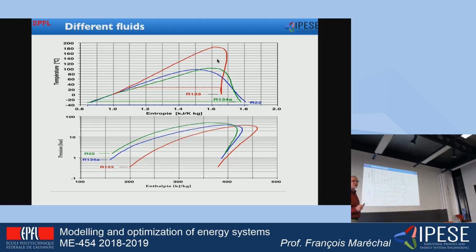Right, so I need equations. When we are talking about equations, there was also something interesting in what you said: as soon as I gave you the temperature and the pressure, you said, I can calculate the enthalpy. Which means that some things need to be fixed in order to make a calculation. Here we know that we need to know 2 things, for example, the entropy and the temperature. This is named the degree of freedom of the system. So it's the number of variables that we have to fix in order to be able to solve an equation.